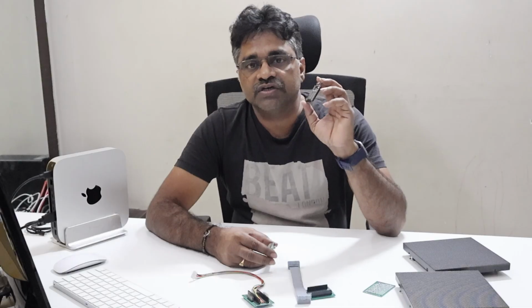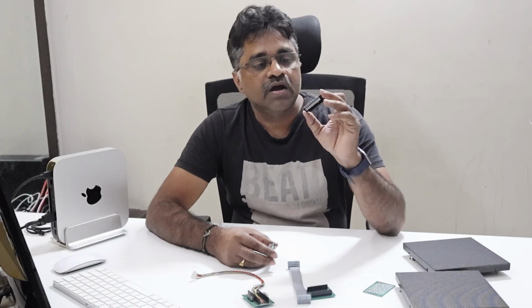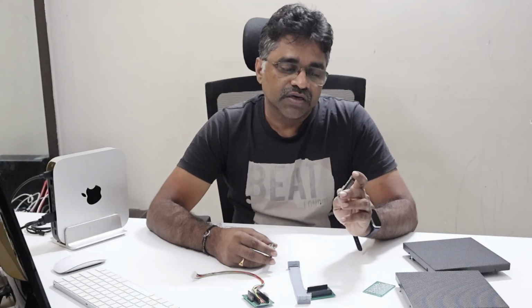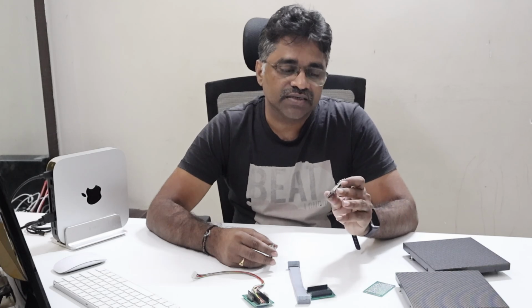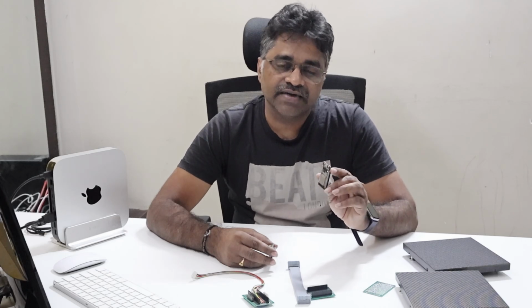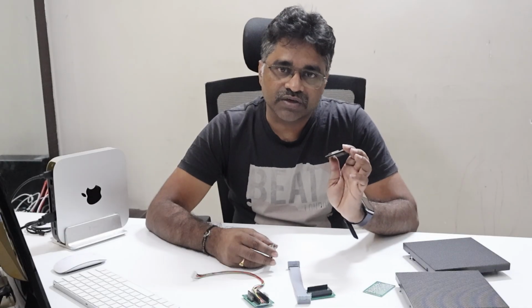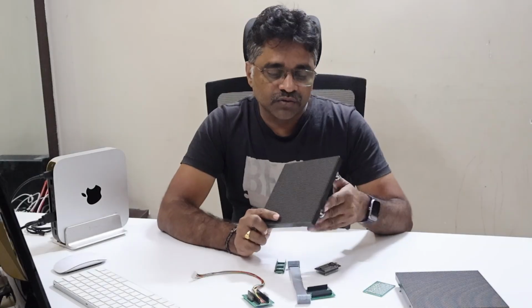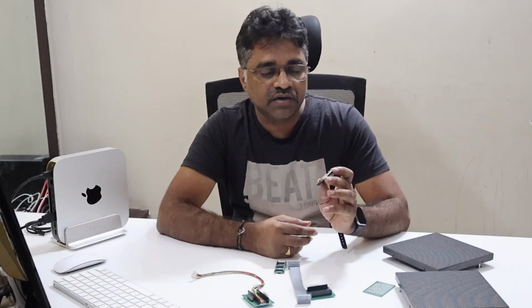Suppose we want to change the program, or send some text from a mobile app, or switch the program; we will be using the Wi-Fi. So then the CPU has to run the Wi-Fi tasks as well as the rendering of the text or content, and then it has to push the frame buffer to the matrix display. All together this becomes a big burden on a single CPU.